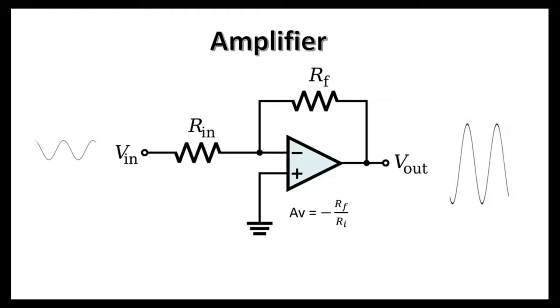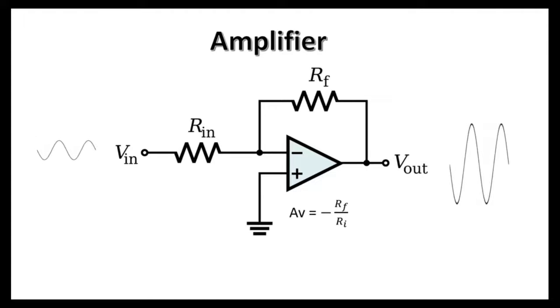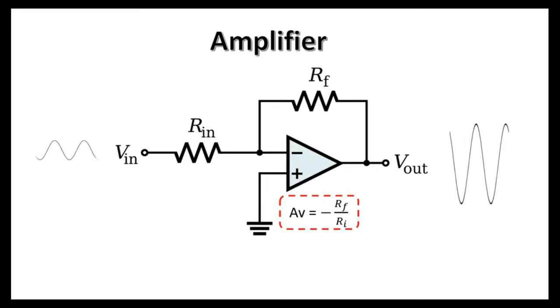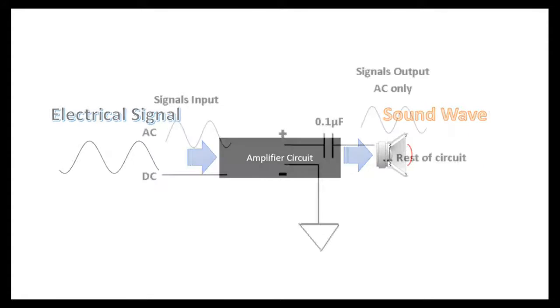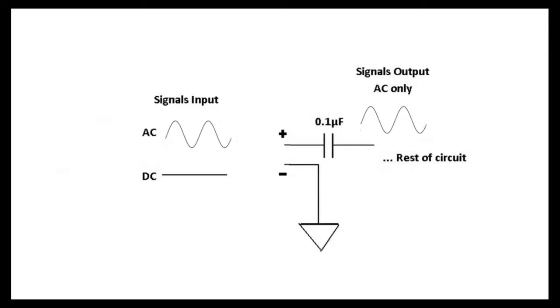For this example, the inverting amplifier is used, and the amount of gain or the amplification magnitude is as follows. Now we can see that the system has changed to incorporate the need of signal amplification. However, a more practical circuit requires a DC filter circuit. This can be done by placing a capacitor as it rejects the DC component of the signal. The DC component in this case is the power supply provided in the circuit, while the AC signal represents our alternating current from the inductor.